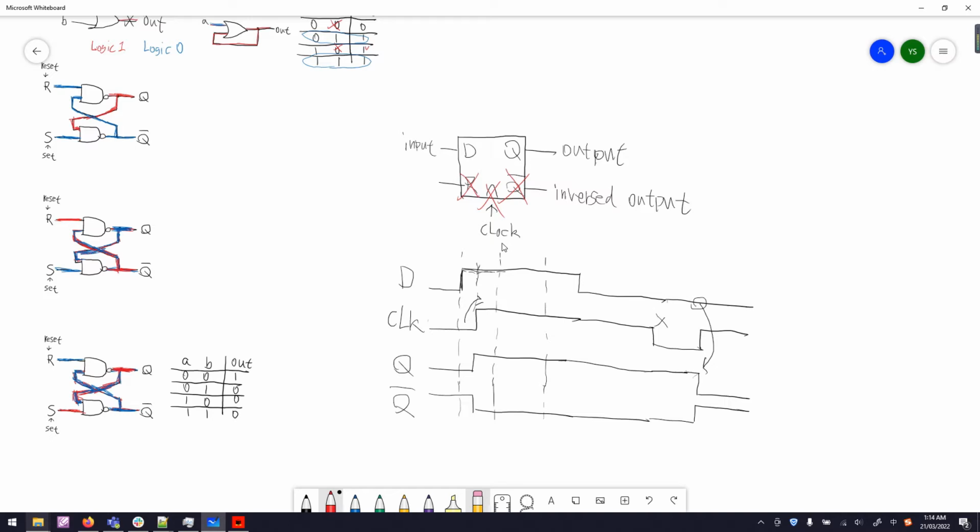If you are using a language like Verilog or VHDL, they are both proper HDLs. You can connect different clock signals to each of the chips. But in Nand2Tetris, we assume the clock pins for each chip are commonly connected, and we don't need to specify which signal is driving the clock pin.